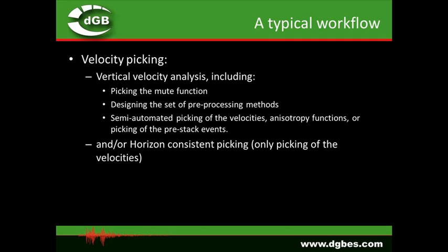Alternatively, or I would say in addition to the picking in the vertical velocity analysis window, you can also use a horizon consistent picking mode that allows you to pick velocities on entire inlines or crosslines very quickly for a number of horizons.